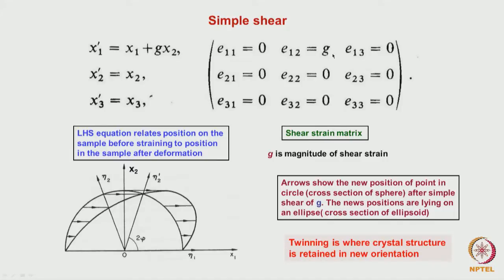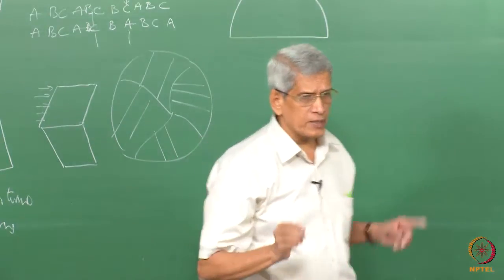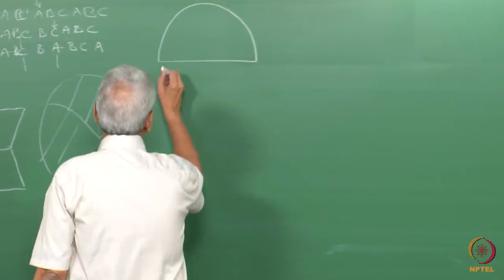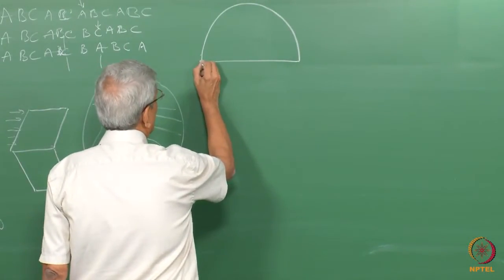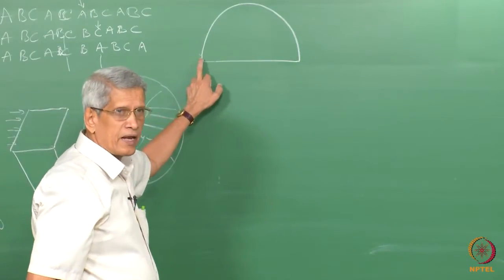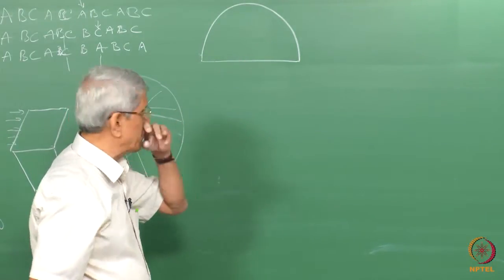What is being shown here is that we assume that the original shape of that sample to be a hemisphere. When we apply this shear, it is called a simple shear, but it is a homogeneous shear. That means that every region will be deformed proportional to the height multiplied by tan alpha, that's the way the displacement will take place.